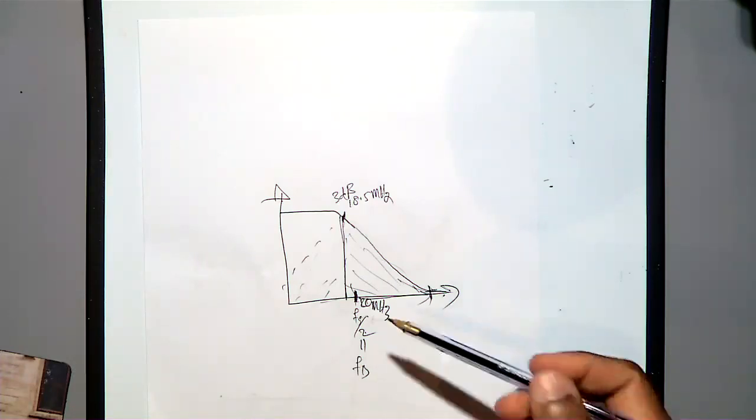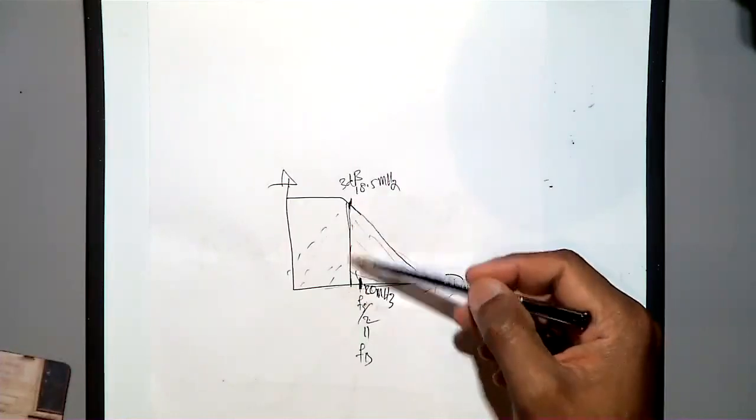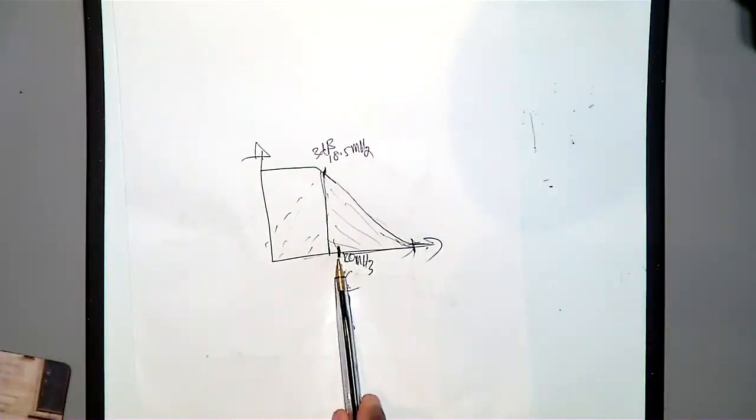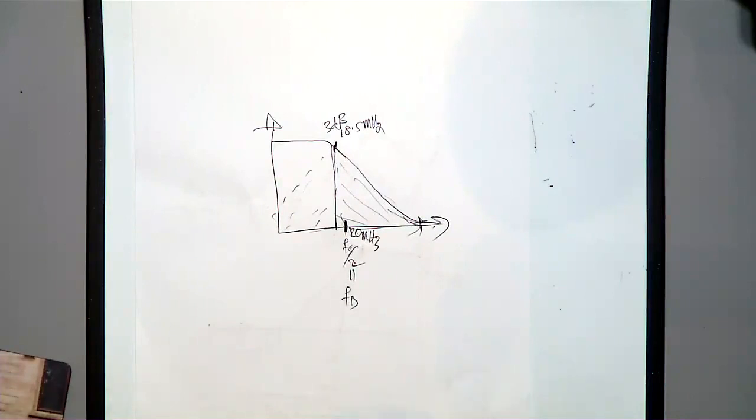So now your Fb equal to Fs by 2, it is quite tight. If you want to avoid this situation, then you can increase the sampling frequency of the ADC, and you get a bit more space. So that is the reason we made that one. In order to understand that concept, we made it tight. But we know that in your DSO, you attenuate, but still some will be folding back.